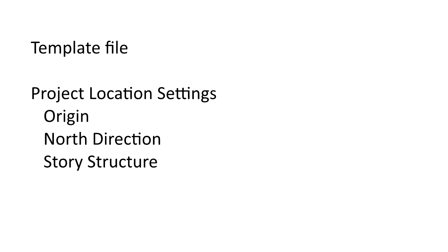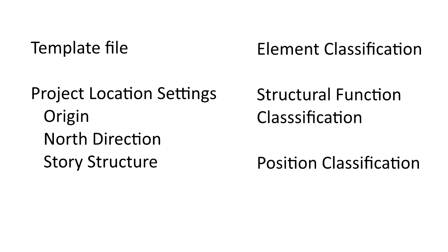A good template file is essential. For all team members to be on the same page, the shared system must include identical project location settings, origin, north direction, and story structure. We also need to properly set up the following: element classification, structural function classification, position classification.